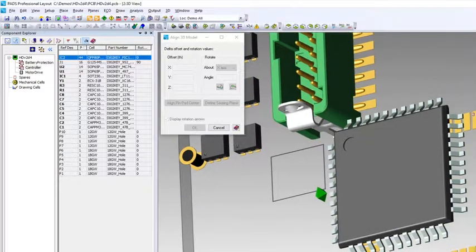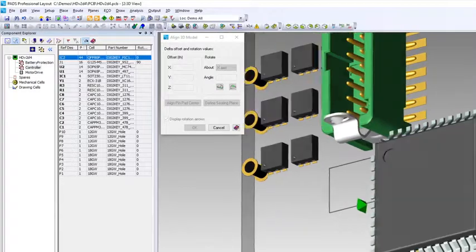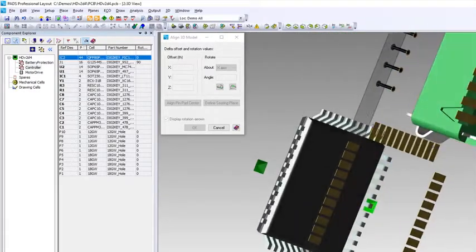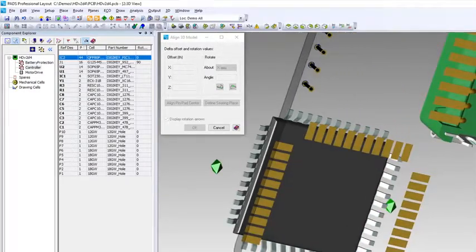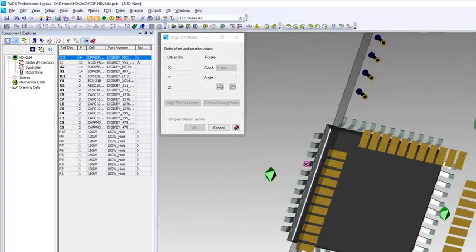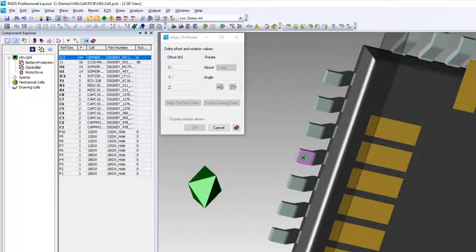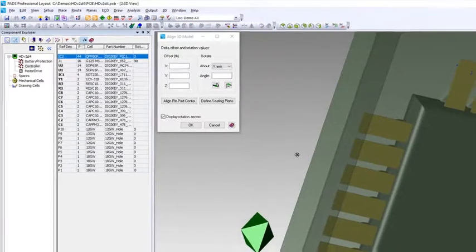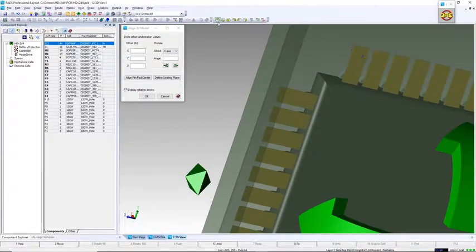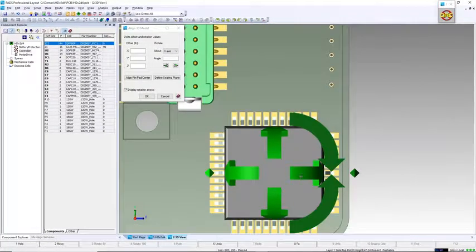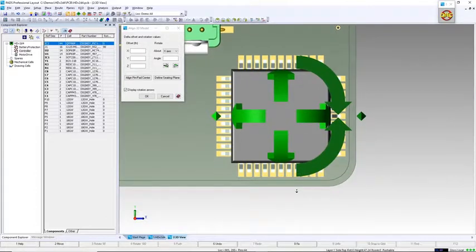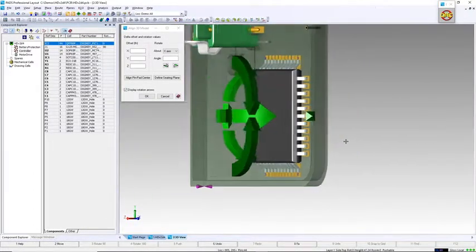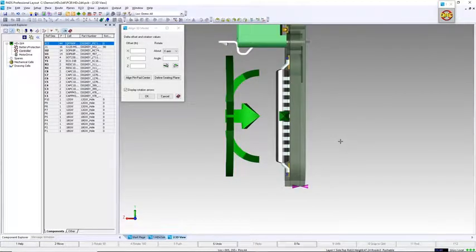Once you select that button, you just rotate the part so you can see the bottom of the pin, select one of the pads on the bottom of the pin, and the part will automatically drop onto the decal as the tool already knows the seating plane of the decal. Check our placement by rotating the board around real quick. We can see that in the Z plane, it's perfectly mated with the copper pads, and in the X and Y, it's mated perfectly in the center of the pins, all with a couple clicks of a button.